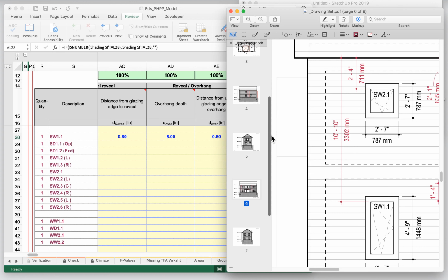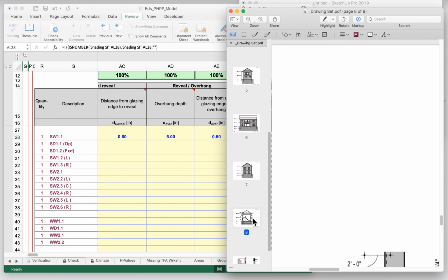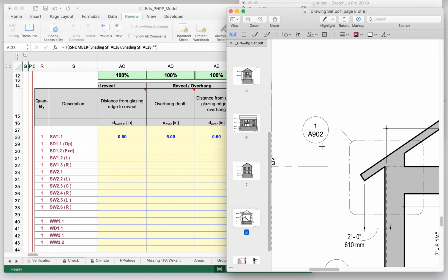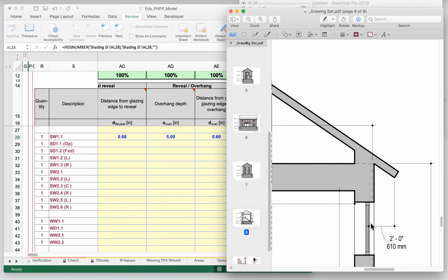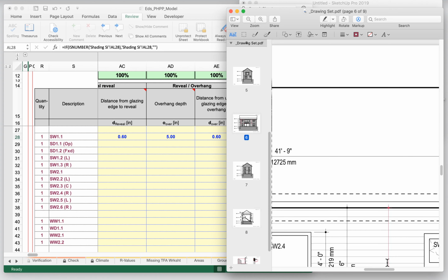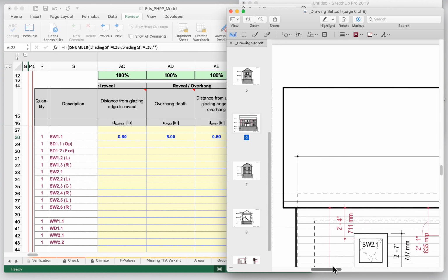Well, we can go to our section view, and just like on the north side, because it is a symmetrical building, we see that all the windows are installed in the same place, so we have a 2-foot dimension from the pane of glass out to the leading edge of that shading object. So 24 inches horizontal, and in this case we were saying 10 foot 10 as the vertical dimension. Let me go back here so we can see that.